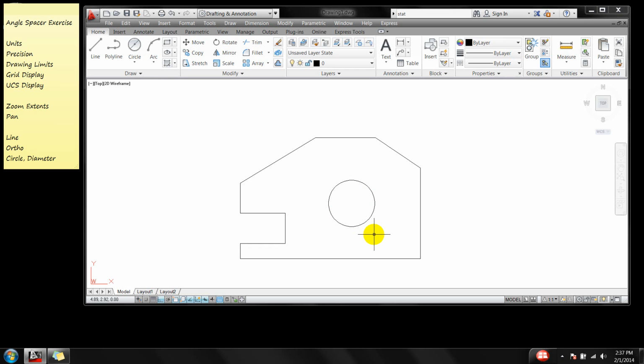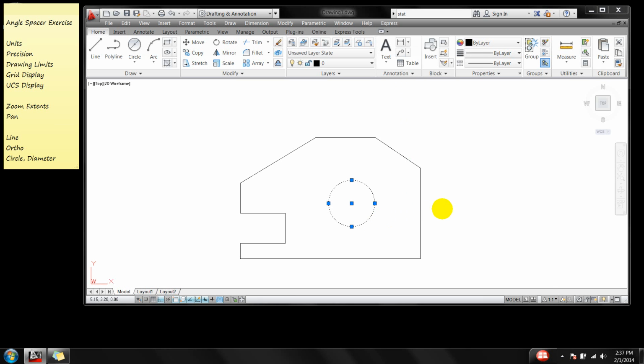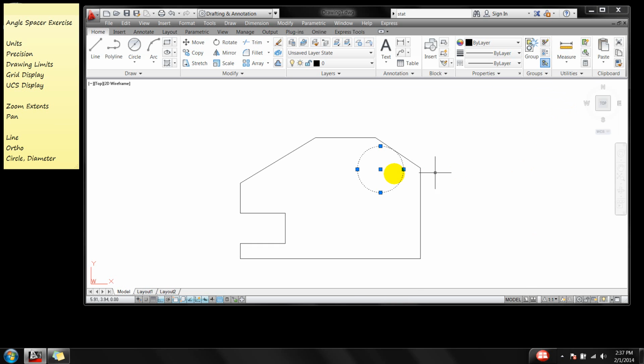Now let's say I wanted to use a coordinate system to adjust that. So I could right click and I can go to properties. And I could key in my X and Y right here. Okay, let's say I want to make this 5 and I make that a 4 and hit tab. Okay, and then we can close that. Okay, hit escape. Well, now this is a little bit cumbersome. Okay, if you've gotten pretty good at it, that might be your way of doing it.